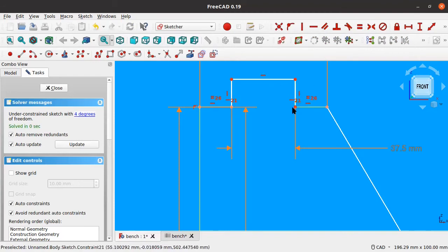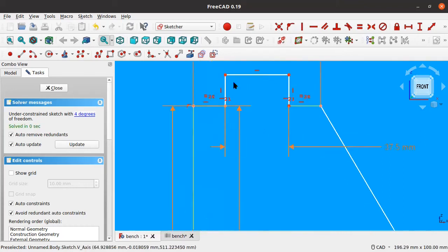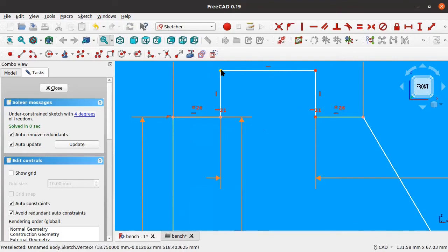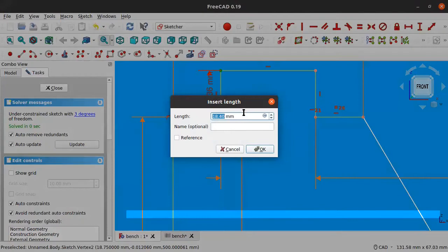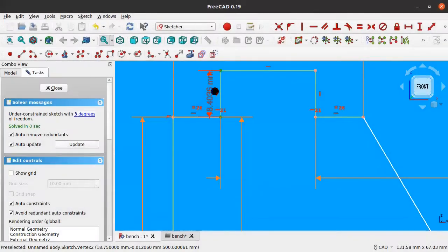And then this finger joint is going to be one layer of the material. This is why we can select these 2 points and set it to the height of the material thickness, which we also have in the spreadsheet. Like so.